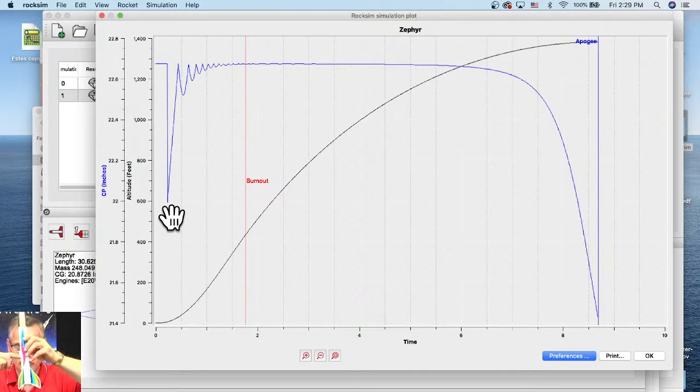It's shifting forward. It goes from 22.75 inches from the tip of the nose, and then as soon as it shifts, it goes to 22.0 inches. So it shifted about 0.7 inches, like from here to here. So it's not much. As long as it doesn't shift all the way in front of the center of gravity, because that's bad.